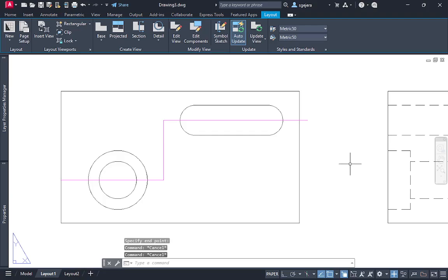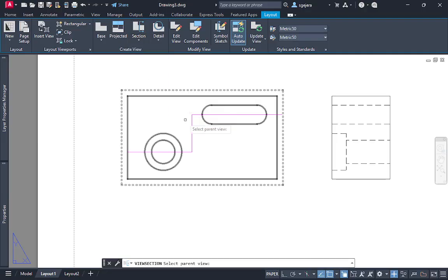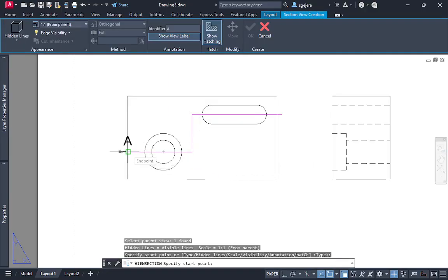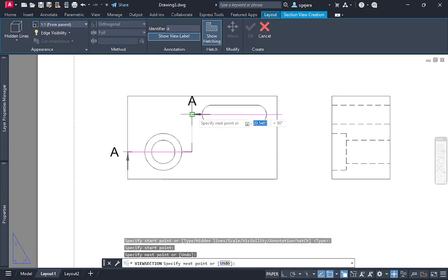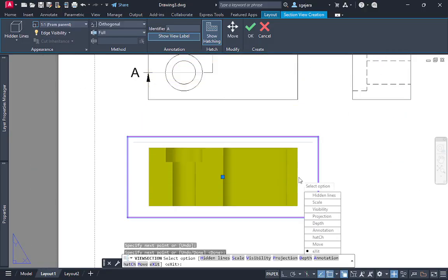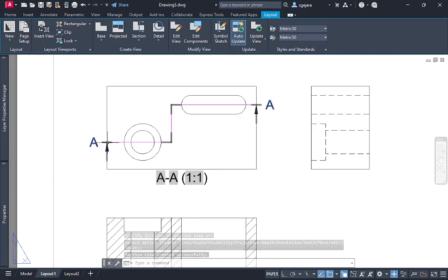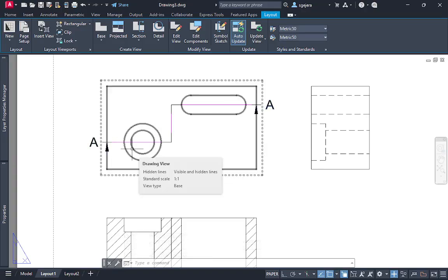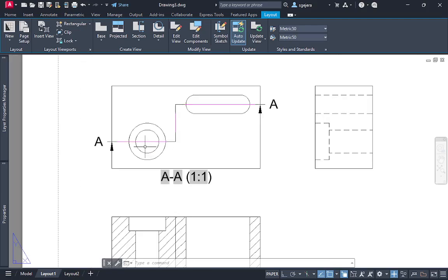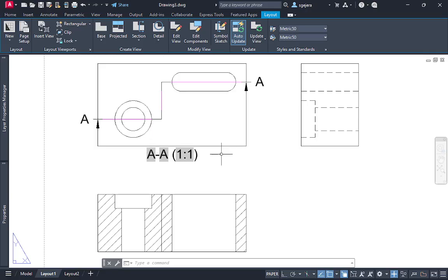You can opt to create the section view first as just lines. Then, afterwards you create the section offset. Now, if I select this, it's easy for me to snap, no? Because I have my guidelines. It's easy to find these points. I can easily track it like so. Press enter. Then, select this one. Press enter again. So, that's one way to do it. If you're not confident with using tracking lines, you can always just create the guidelines for your offset first, then create the offset section view afterwards.